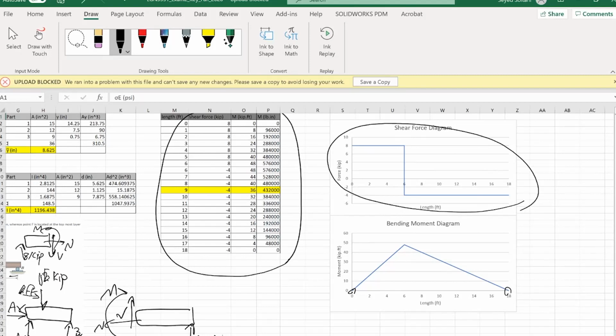Just take a look at the shear force. This is the derivative of the bending moment diagram, which means that for the segment AC, I'm talking a curve whose slope is uniform. It has a positive uniform slope of magnitude 8 KIP. What would that be? A line, right?